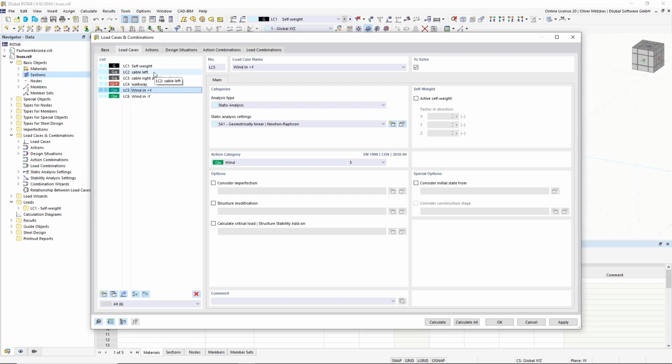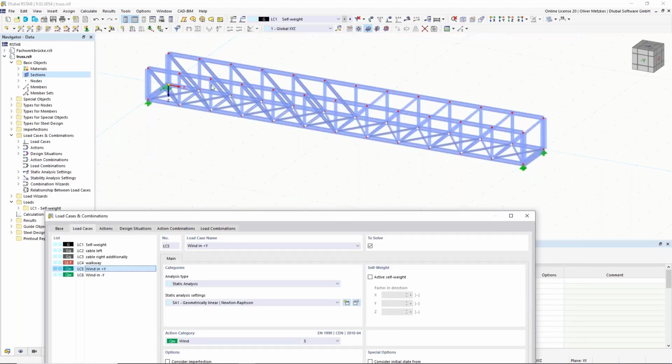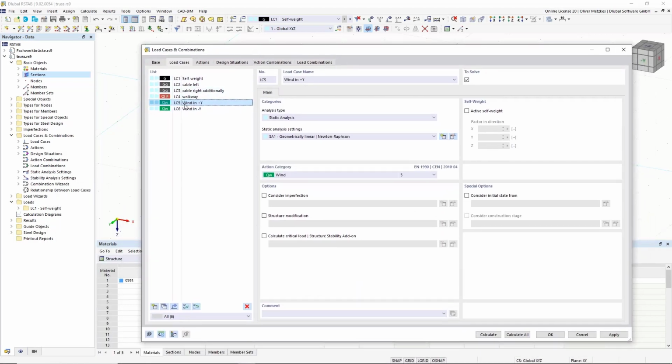I don't have, for example, temperature loads, to simplify it a bit. Also, in my structure, as I have modeled the supports this way, a temperature load would just increase the length, but there would be no internal force from that if I have a uniform temperature load, for example. So I would say for now, that is okay to have this simple structure of load cases.